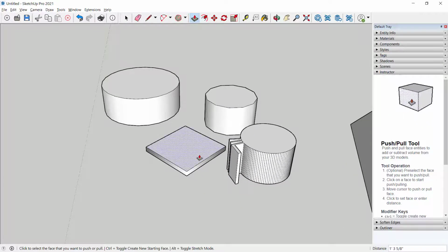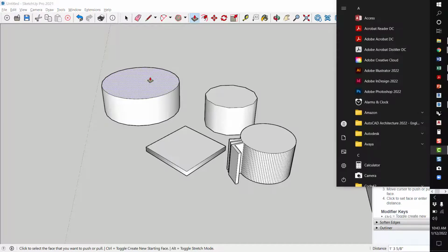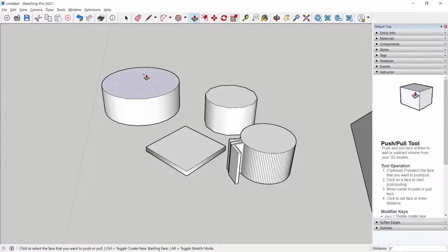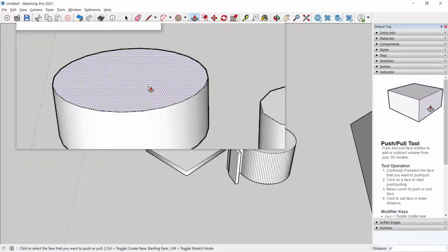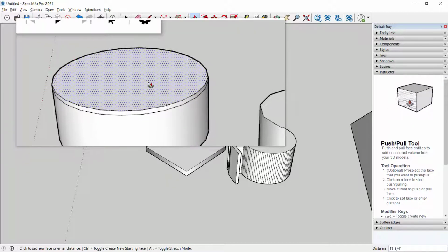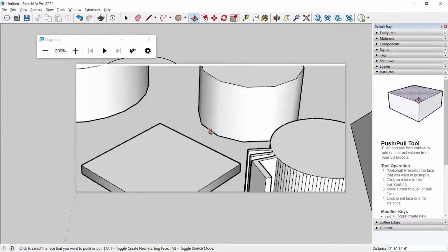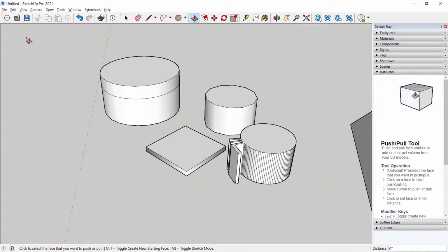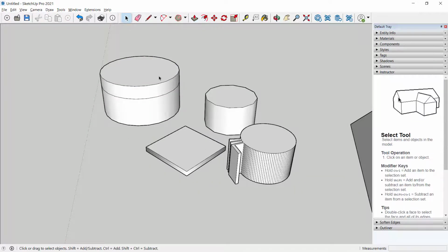So the other thing that you can do is if you hold down Control and tap push-pull. This is one of the options that you'll see down at the bottom. I'll tap Control. A little teeny tiny plus sign shows up next to my cursor. You can see it there. That little plus sign indicates that it's going to make a copy. I'm going to hit Escape here to get out of the zoom mode. And you might say, well, why would you do that? I don't need a copy.